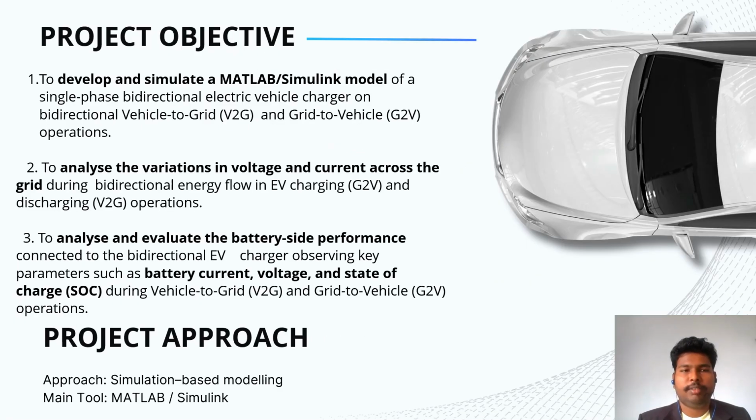The project objective is, first, to develop and simulate the MATLAB simulation model of a single phase bidirectional EV charger for bidirectional operation. Second, to analyze the variation in voltage and current across the grid during the bidirectional charging operation. Third, to analyze and evaluate the battery side performance connected to the EV charger, observing key parameters such as battery current, voltage, and state of charge during the bidirectional operation. The project approach is simulation-based modeling, and the main tool used is MATLAB Simulink.